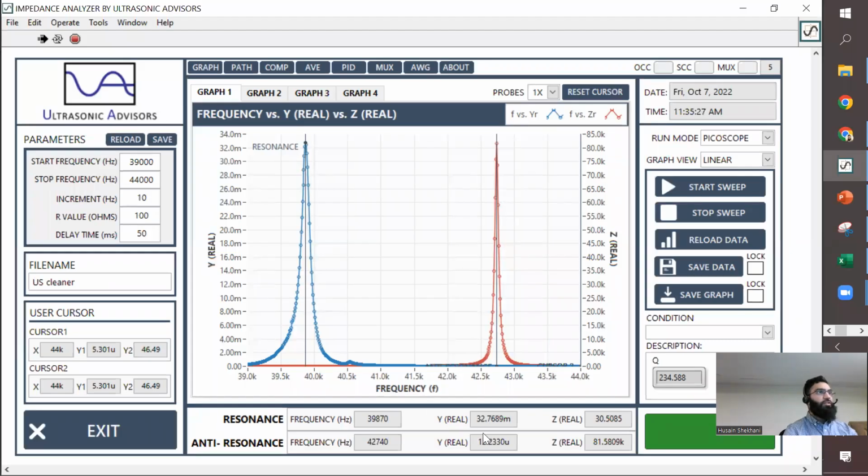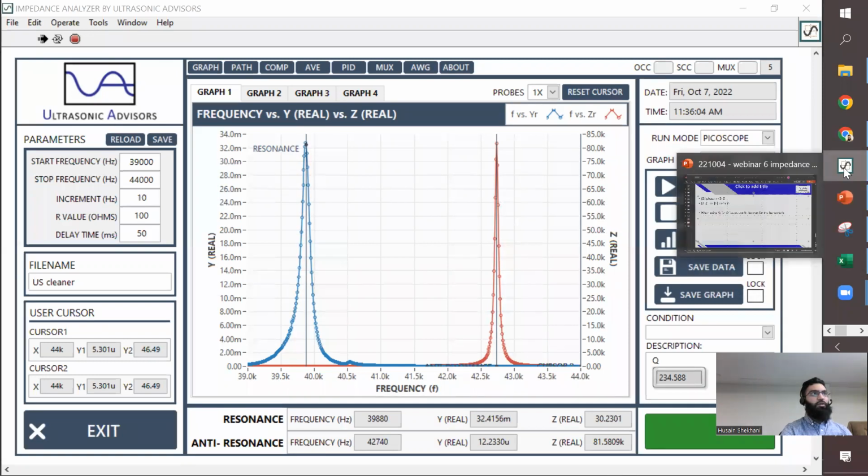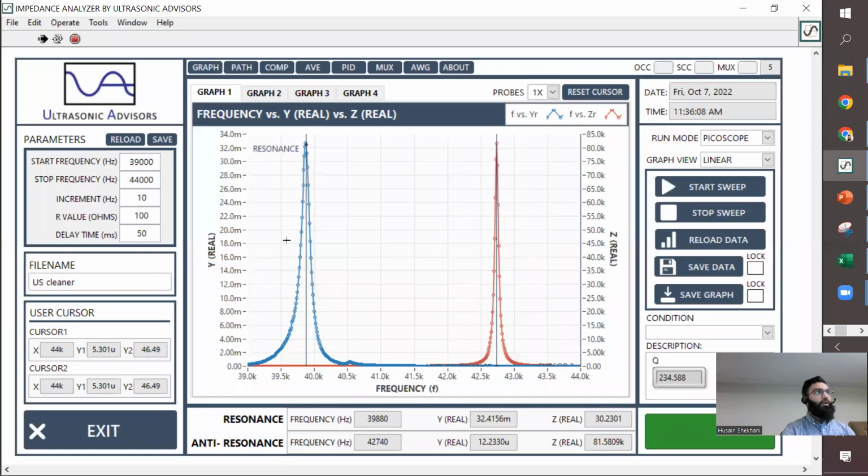You use half. So if this is 32 millisiemens, like this is the real, then you go down to 16, right? I'm looking for 16. I got it. Here's 16 right there. So that's how you calculate that. You go off peaks, which is much more intuitive. I find that a lot of people get confused between all these peaks and things. This is a huge point, and I can't emphasize enough how you can get messed up by doing it incorrectly.